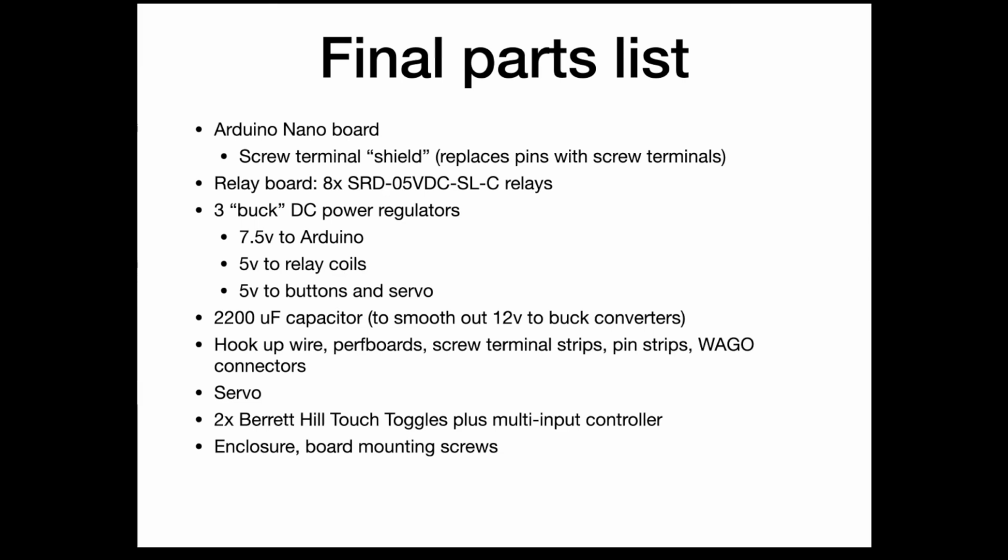One relay board works the way I wanted it to. So when the Arduino writes a signal to the relay, it toggles, it switches. There's another one that works actually like a flip-flop. You send it a signal and it remembers its state, and you have to change it by sending it another signal. So I had both, but this model relay is a lot easier to program.